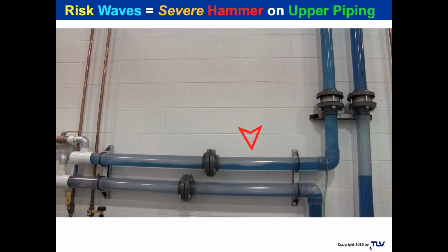So here you've got the top pipe. Now it's a short distance of pipe. What is it, 10 feet? Not even. And we've got very low air pressure in here, so you're going to have an aerodynamic property, the air will not collapse the way steam would collapse. So it's not the same as thermodynamic. But even so, take a look at this water and watch for the slugs. Here it comes. Bam.